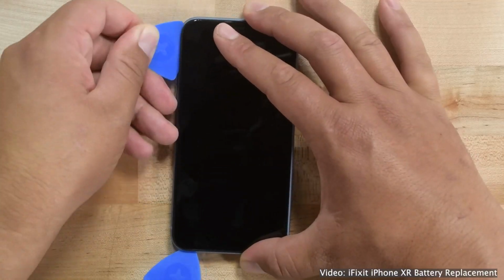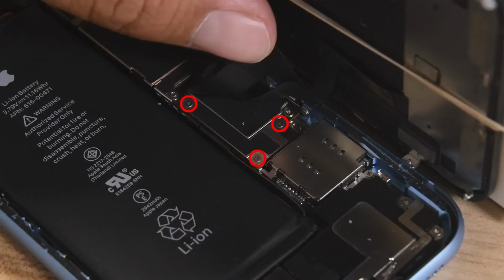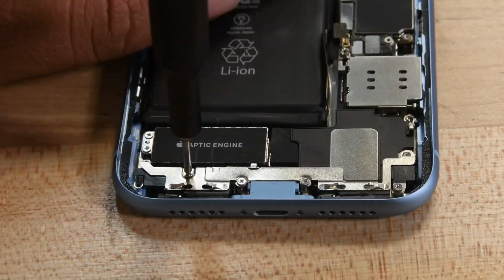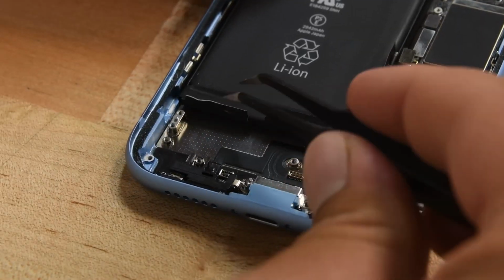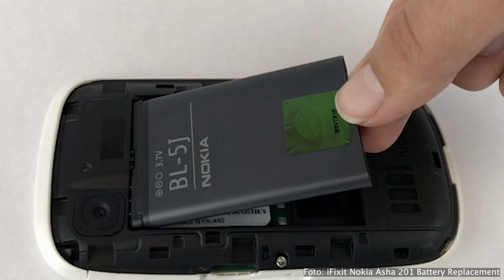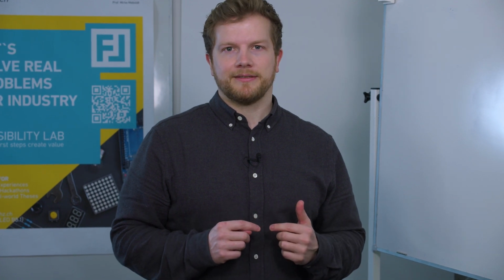Disassembly depth means how many disassembly steps are necessary to repair a crucial, so-called priority part, for example, a smartphone battery. Do I need 20 steps to take out all the smartphone components until I finally reach the battery at the very bottom? Or can I just open the back of my smartphone and quickly access the battery? The latter is definitely more repairable. The smart use of modularity, stacking and packing can significantly reduce your disassembly steps.